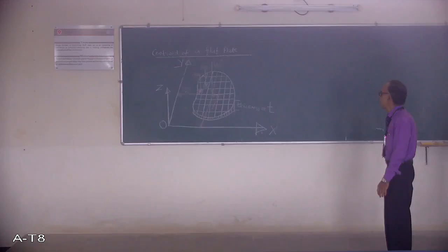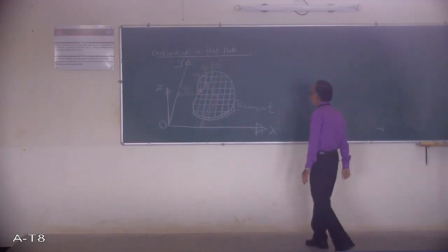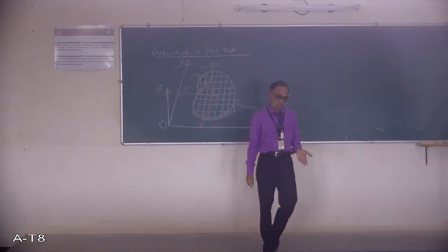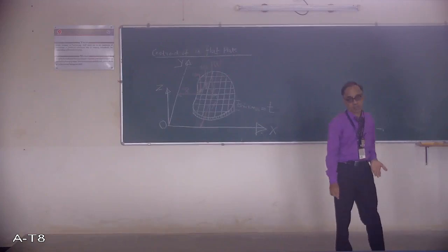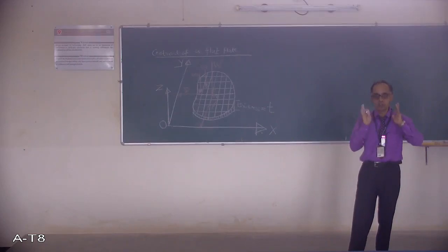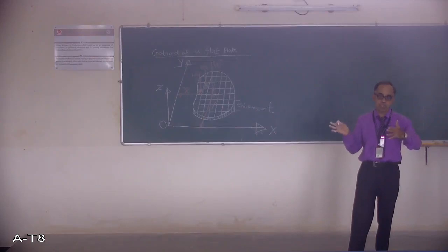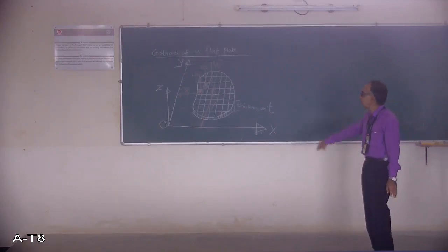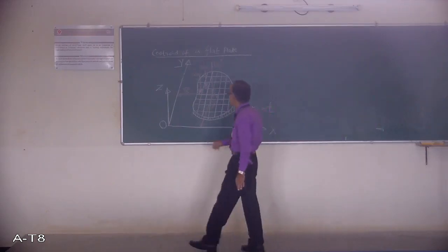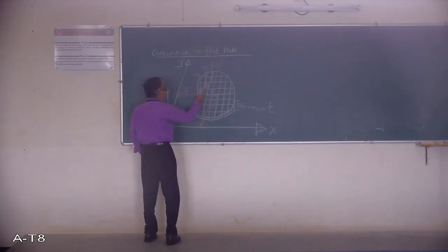Okay. So now the total weight of the plate is acting exactly at the centroid G. You have already learned in the previous chapters what is called the Varignon theorem. Okay. The Varignon theorem says the moment of the resultant is equal to the sum of the moments of the individual forces about the same axis or same point. Now how do I apply the Varignon theorem here? W is the total weight, that is the resultant. The same plate, I divide into a number of small parts.